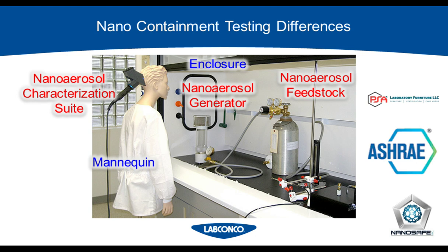So using a combination of both those concepts, we actually can assess nano containment using some modified components. Obviously, the first thing you need to do is change the gas out for a nanomaterial. Then you have to have a generator that's compatible with the nanomaterial. And also, you want an environment that doesn't contribute any background noise. With ASHRAE 110, sulfur hexafluoride is used because it's not available within the environment, so it's not naturally produced and can't be a background contaminant.